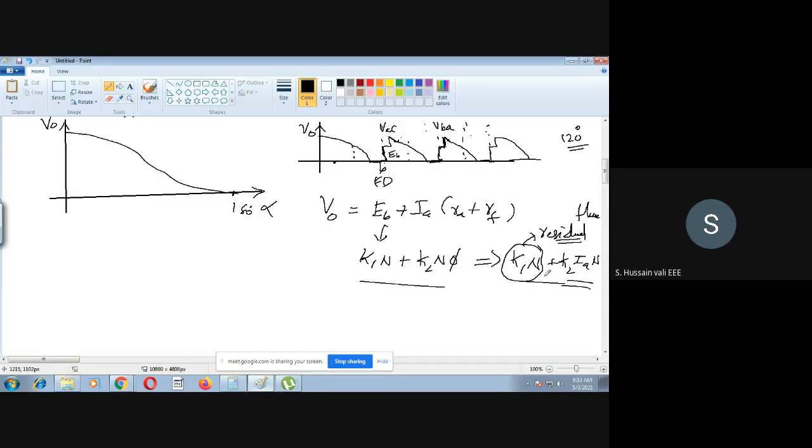This is because of the actual field now. Okay. And then we have one more relationship. What is that relationship? Torque is proportional to Ia square in case of your series motor. So we will get Ia value from this and we'll substitute Ia here. Then that entire EB will substitute here. Ia also will substitute from this equation, T proportional to Ia square. When you do all this shuffling, then you will get a relationship between speed and torque.